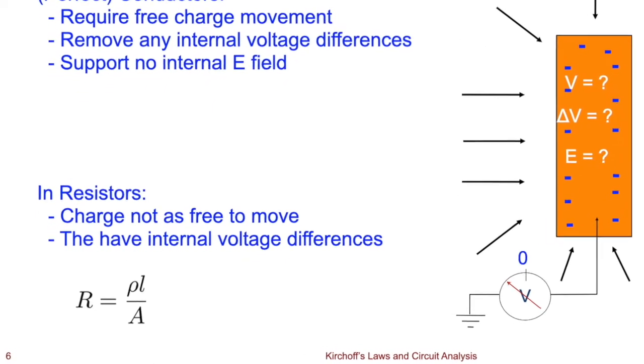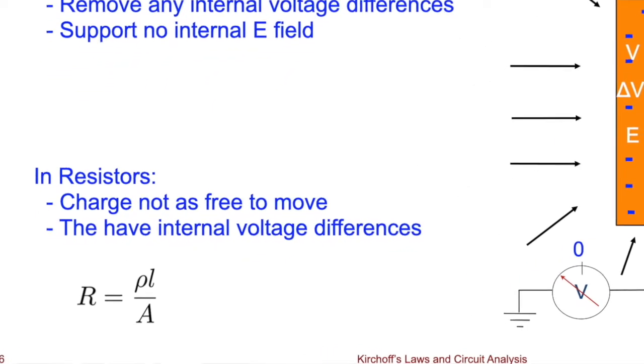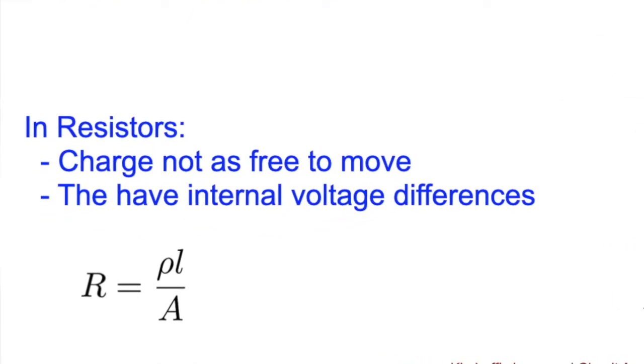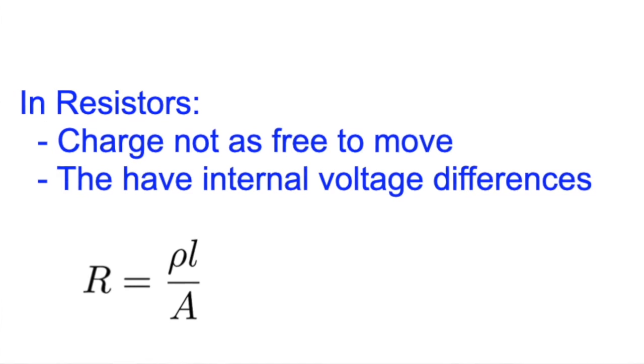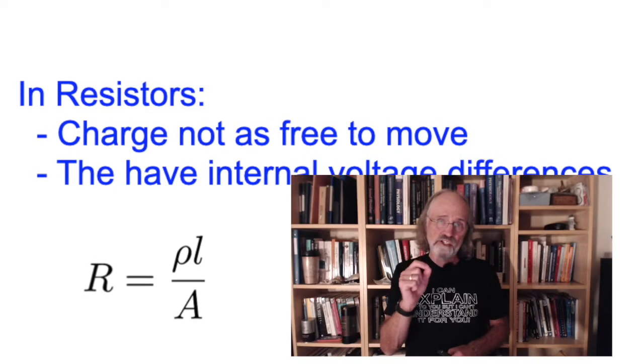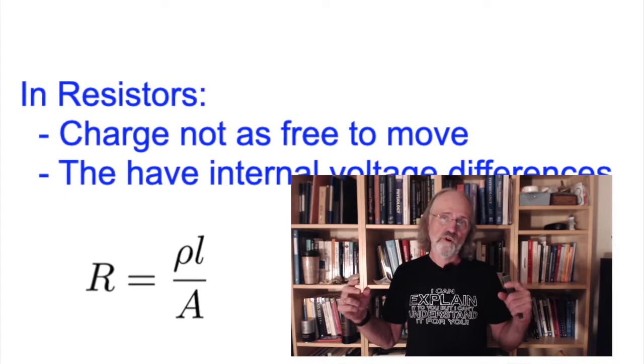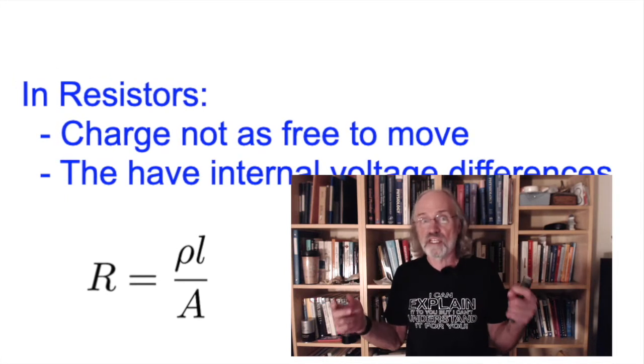an equation. This is one of many equations we can write that says the resistance is a function of resistivity, and that's that rho value. That's a characteristic of the material that the object's made of. And then, without too much imagination, we can imagine that if the object is longer, it's going to have more resistance. And it turns out it's a roughly linear relationship.